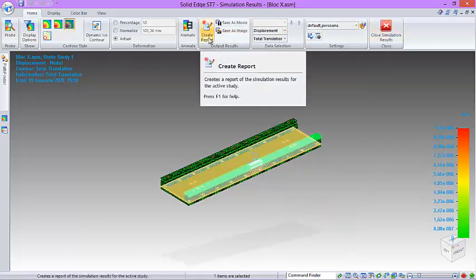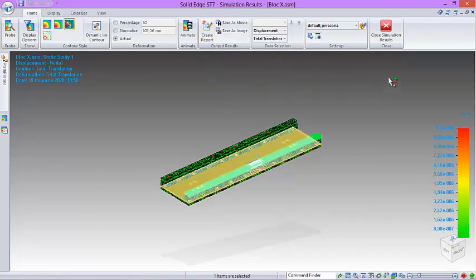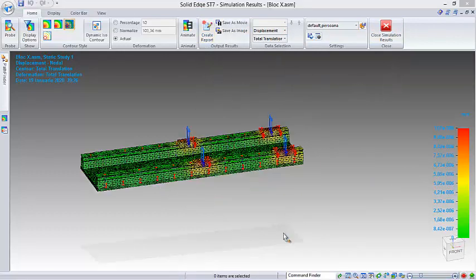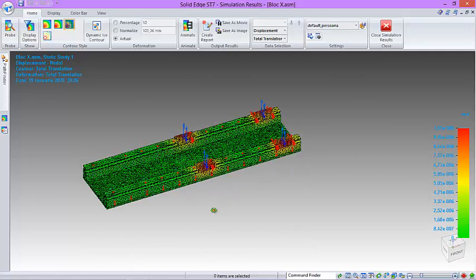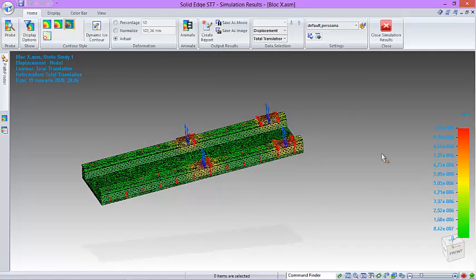We're going to create a report with the create report option, and this is a simulation of all the 4 cages being pulled by 4 times the force, and that's 140,000 newtons. As we can see, the total displacement is still within 1 by the power of -5, so that's more than microns. And the factor of safety is still over 2000, so the simulation passes also.